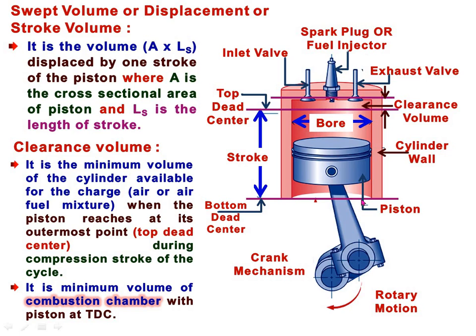During the exhaust stroke, we are sweeping off the burnt gases from the cylinder. At that time, the piston moves from bottom dead center to the top dead center. So the volume between bottom dead center and top dead center may be termed as swept volume or displacement volume or stroke volume.